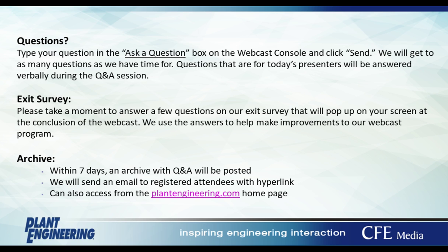And if you can use stop categories 1 and 2, which relate to controlled stop, it usually means that the risk either requires that the machinery be controlled during the stop to actually help with the safety, or that the hazard is, I don't know how to say this, kind of low enough, the risk assessment results are low enough where controlling it for a time period does not increase the risk. So it's not a simple question to answer, but yes, you do have to go through the risk assessment to get to the point where you're determining the stop category.